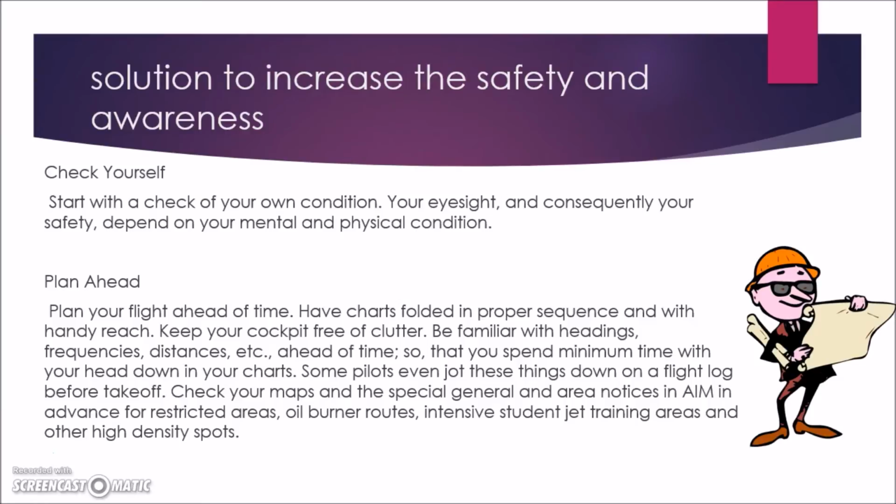Plan your flight ahead of time. Have a chart folded in proper sequence within handy reach. Keep your cockpit free of clutter. Be familiar with headings, frequencies, distances, etc. ahead of time, so that you spend minimum time with your head down in your chart.